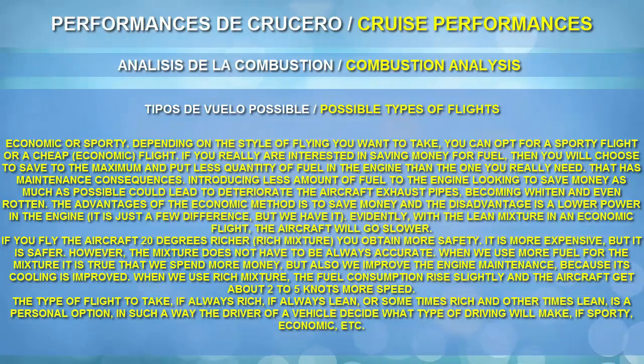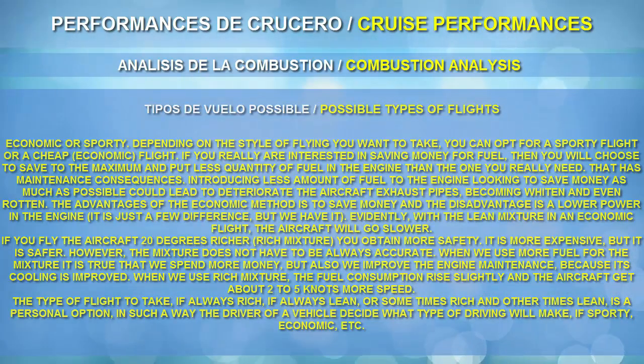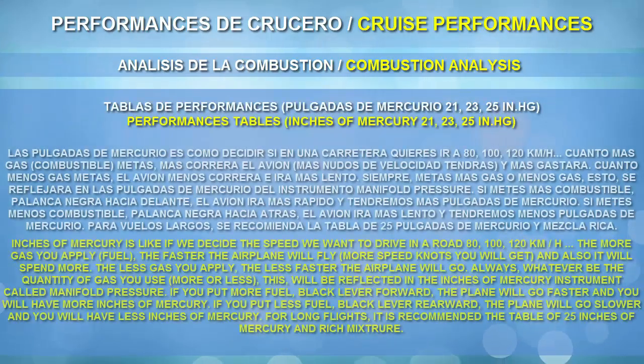To fly rich always, because it's better for the engine cooling, it's better for your safety, it's better for the engine maintenance, and the fuel consumption also won't drain you. It will rise slightly, so it won't be extremely expensive. So it is recommended always to fly rich. Always. So basically, when you reach the EGT point, the EGT peak, remember that that is a reference point: you put the needle in its higher position and then fly rich.